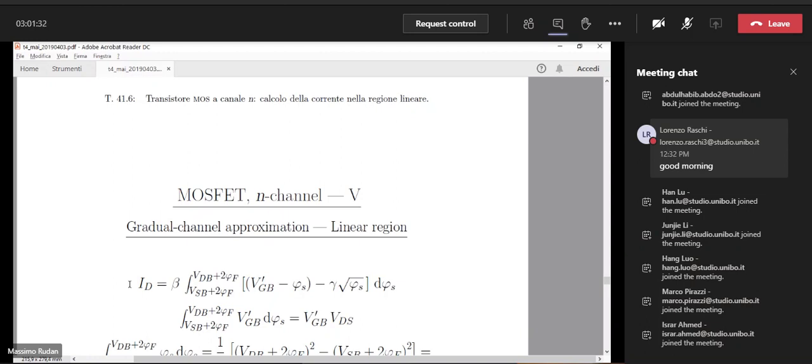And finally, we have plus the derivative of ID with respect to the gate voltage, again, times the variation in the gate voltage. So we have a current that is the sum of 3 currents in the small signal circuit, okay? Because the differential has 3 terms.